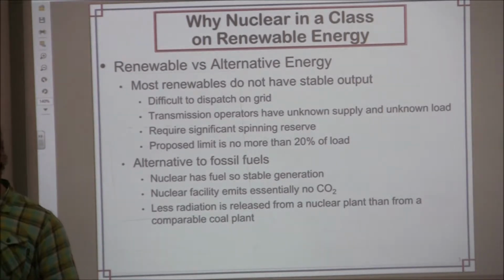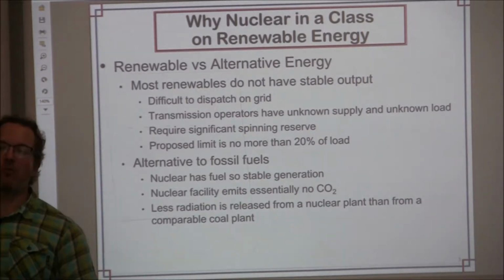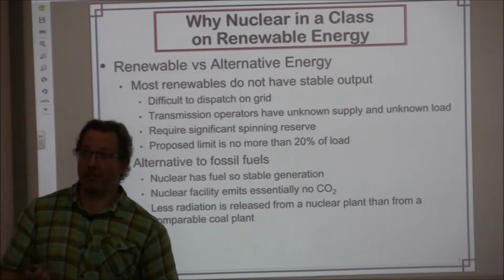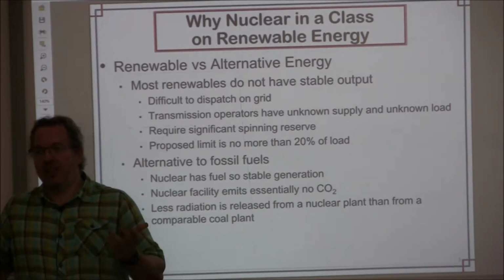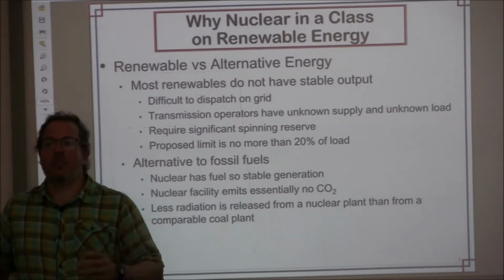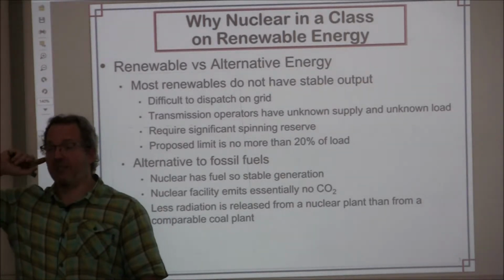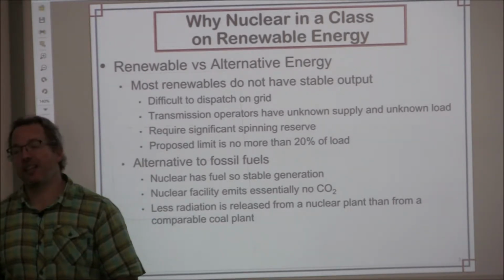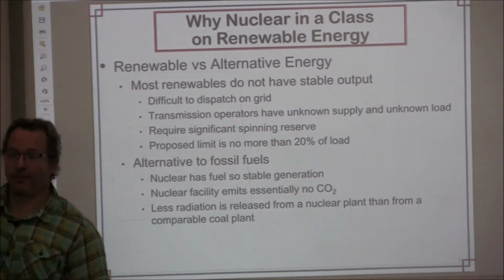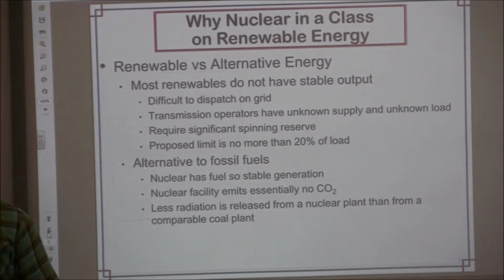If those are small European countries, they would have so much overcapacity for wind, for example in Denmark. They would have so much overcapacity, let's say 40 to 50 to 100% capacity. So even if you lose half your generation, they still have twice what they actually need. They have significant amounts of spinning reserve, so they're able to make do with what they've got.